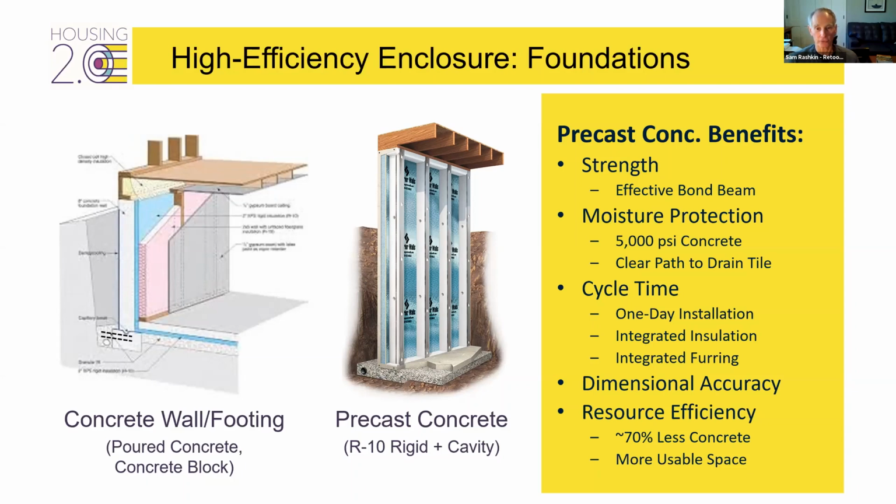I can build it faster with less construction time. It's more dimensionally accurate. It sets perfectly true. There's some extra work in the field to make sure it's ready to be set perfectly level. And then it uses 70% less concrete than a poured concrete foundation. So when we start going to zero carbon, we really have to think about these kinds of solutions as well.